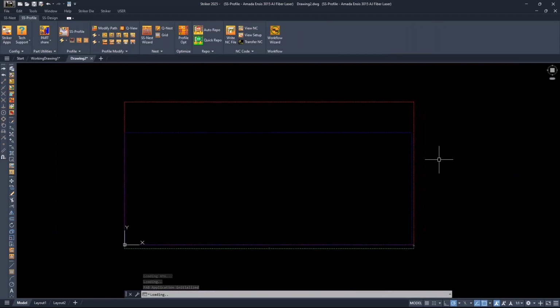The workspace layout looks very similar, except I just don't have my work clamps down here. And how we approach this from a cutting standpoint, a laser generally is much easier to program than a punch, okay? Because you don't have to deal with all the different tooling considerations and forming considerations and rolling tool considerations and how you are going to handle text and so on.